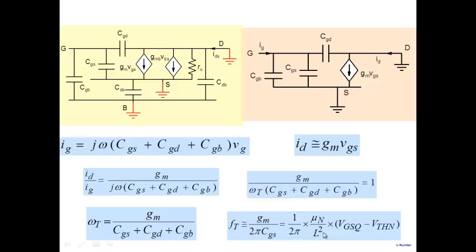As the MOSFET becomes faster, all your digital circuits, analog circuits, everything becomes faster. And the other reason is, as you shrink the channel length L, you can shrink the W also. So overall the MOSFET becomes smaller. And when the MOSFET becomes smaller, you know that you can pack more transistors in a given area. So you can make more and more complex circuits. So channel length scaling has been one of the dominant features of electronics starting from the 1960s.